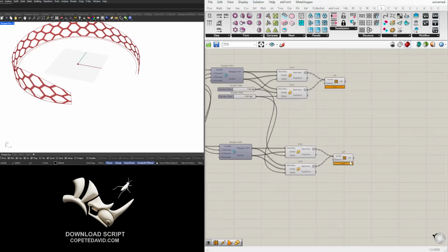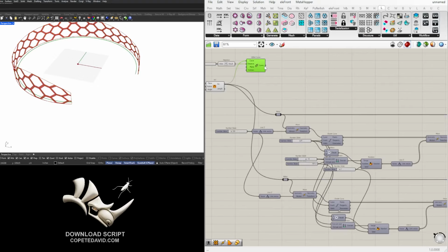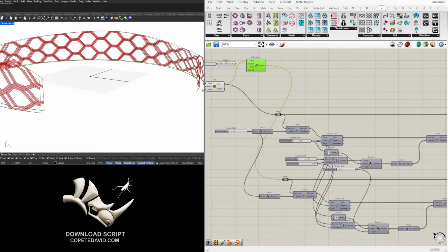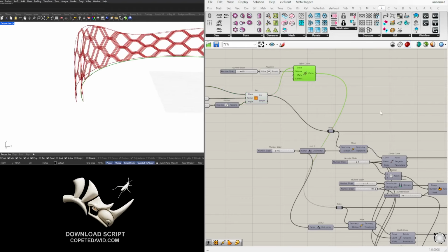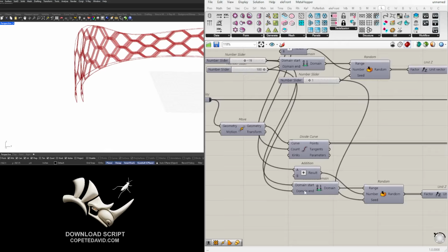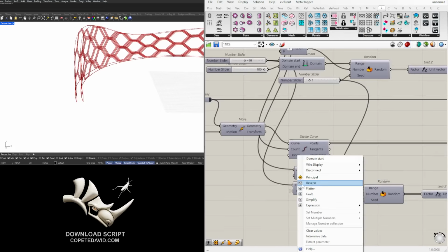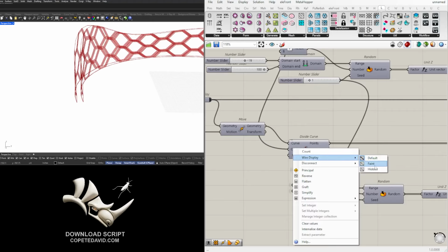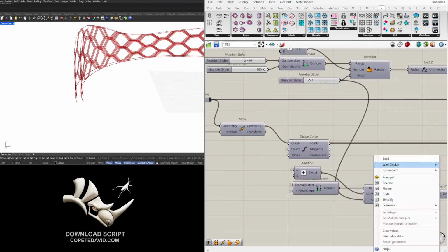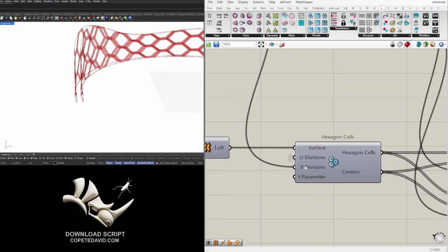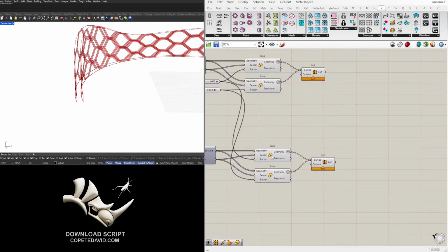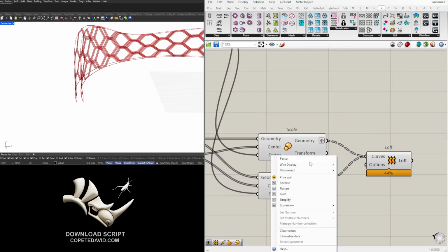And now when we look at this one, so we have the offset curve, this one is going to go on this one. Notice that the exact same thing that we did for this outside curve, we did for the inside here. And some of these wires are definitely going to be messy. So that's why the ones that I copy, it's okay if I disable the wire display so we don't create a mess. And here, the same subdivisions. So this way it lofts together and it comes together into a solid without having any issues.